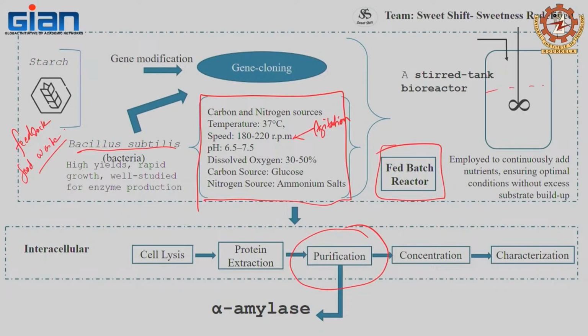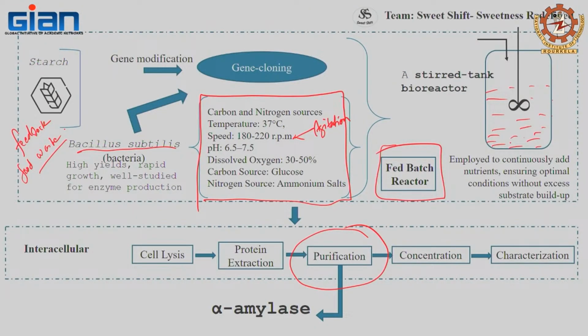No, but see, the reasoning is that when you're looking at feedstocks, for example, in the previous session when we were having the conversation, we talked about the monoline protein if it is added in the food product itself, and then we can definitely do pasteurizations. I think it was the third group that suggested that. But for the pasteurization, you're going to use heat exchangers. If you have protein in it, it might change its structure, and that might lead to flocculation, and the efficiency of your heat exchanger will reduce. So what will you do?